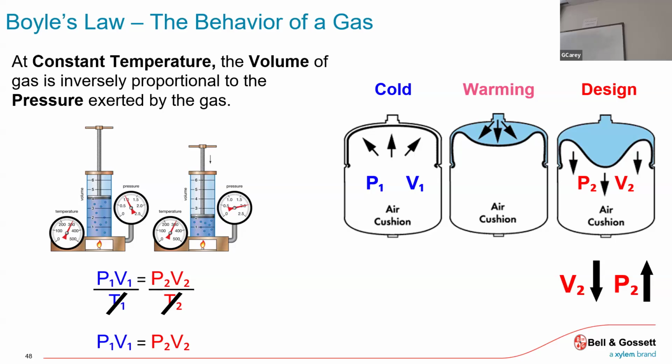What would happen is as it ruptures, air gets released, system pressure drops. So now our feed valve senses a drop in pressure and brings in more makeup water because you told me to be set at 12 or 18 or 25 or whatever it was. So it brings more water in, and all we're doing is filling this big wide diameter piece of pipe. So now when I go to heat that water, I have no room at the end, the relief valve blows.